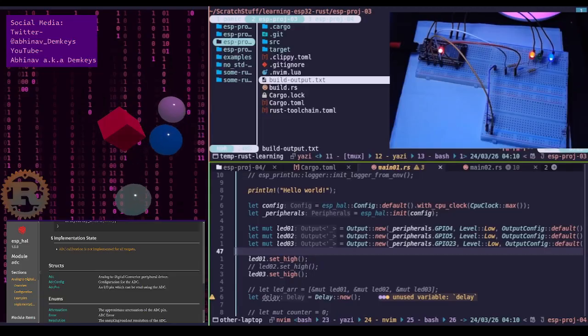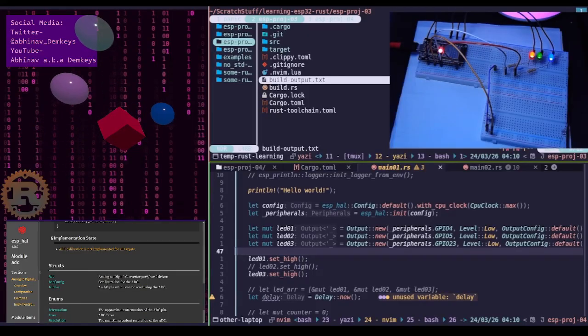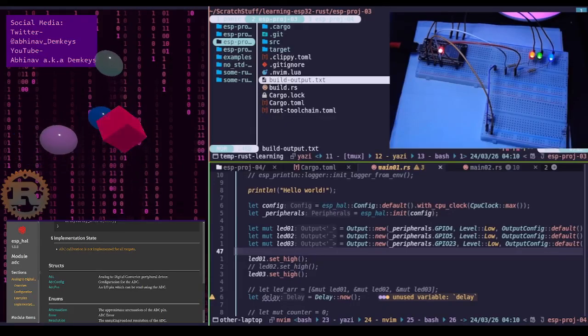This is called nonlinearity. If you try to measure 0.05 volts, the formula might stay at 0 volts because the ADC hasn't woken up yet. For the best results, with your manual mx plus b math, try to stay in the sweet spot between 0.2 volts and 2.5 volts.